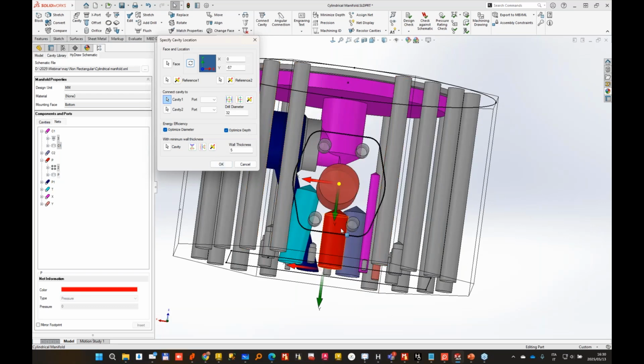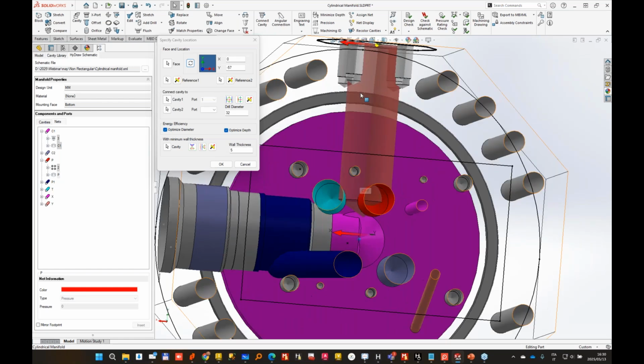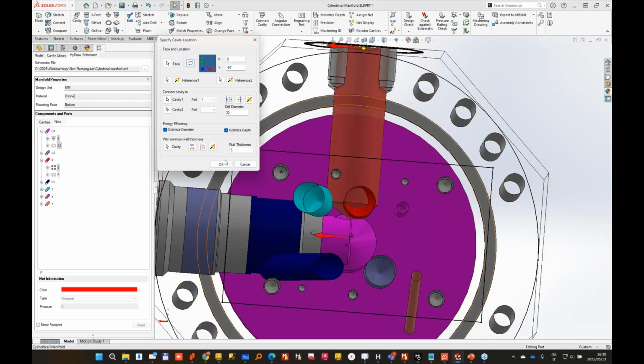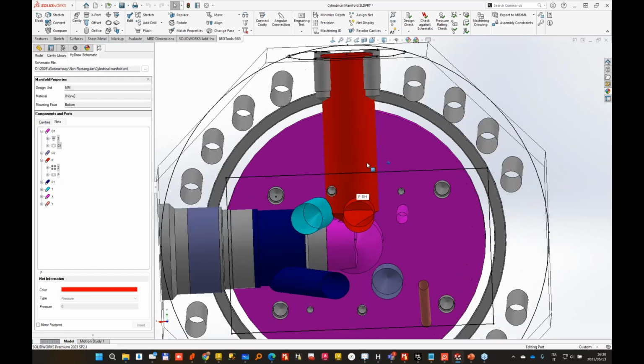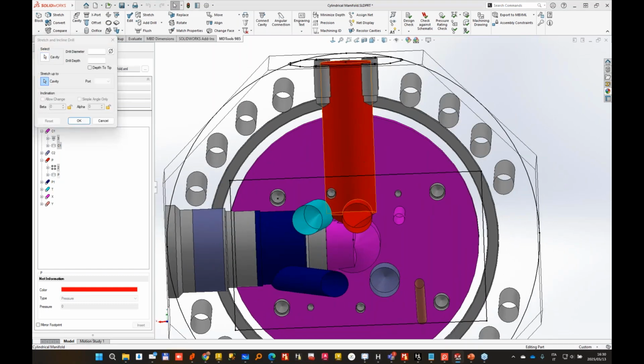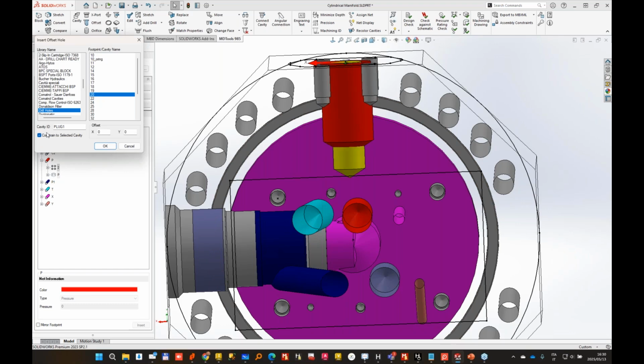It is possible to directly do a connection if you want. Now this will be a bit dangerous because we have other drills, but I'll handle this situation in a different way. And now I cannot really go with this full drill depth, so I need to stretch the drill. I'll make it 50 millimeter deep, and I will add an offset hole. So in this case, it's just a technique. I'll add a 20 millimeter offset hole,